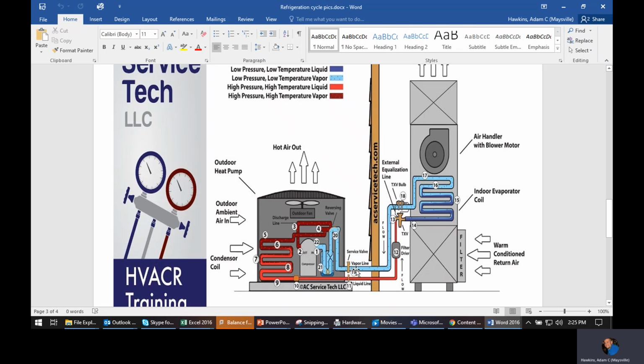So a question I would ask you to think about is: is superheat latent or sensible? Well, we've already said that it happens after the latent change stops. So if it happens after that and it's additional heat added after that, then it's sensible. Well, if it's sensible, it's measurable with a thermometer. And if it's measured with a thermometer, then that means it is just degrees.